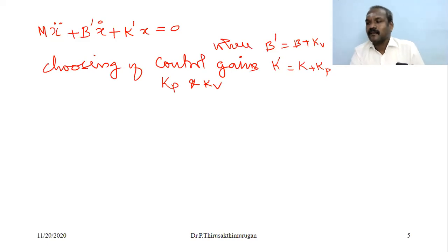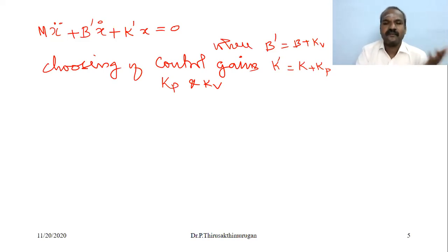We can cause a closed loop system to appear to have any second order behavior that we wish. Using these controller gains, we can control any second order system. Often these gains would be chosen to obtain critical damping. Normally, critical damping.